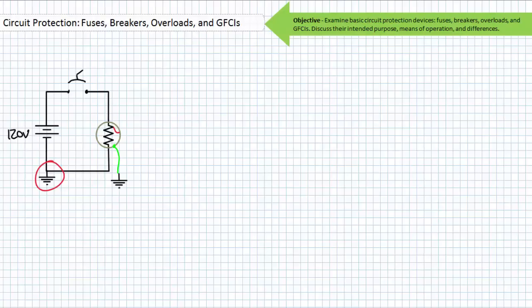Additionally, the equipment grounding conductor, by connecting the frame to our reference upon which operators stand, limits something known as the touch voltage to that same ground potential. Bonding the frame to ground purposely creates a low resistance path to ground so overcurrent devices like fuses and circuit breakers can operate, and operators always touch things at the same potential as what they are standing on.